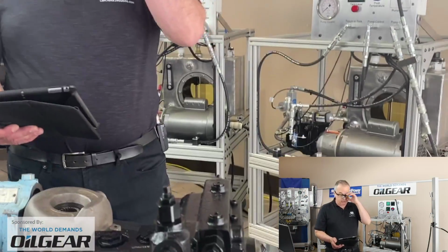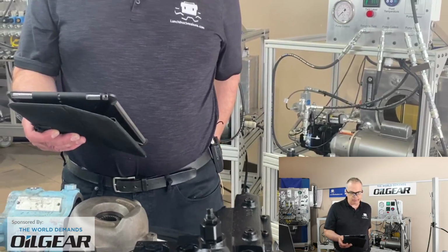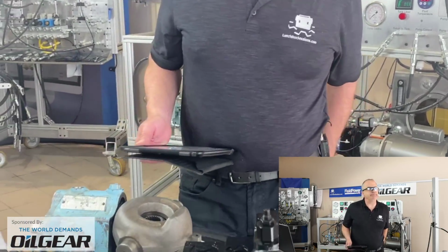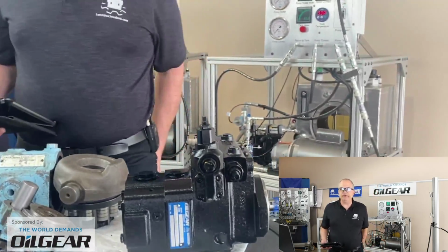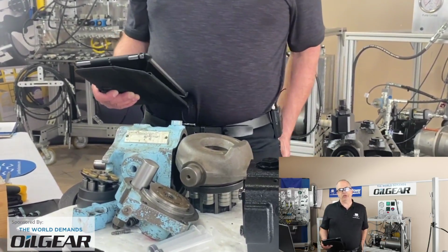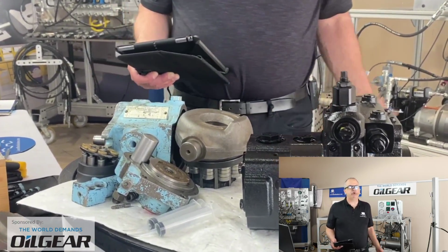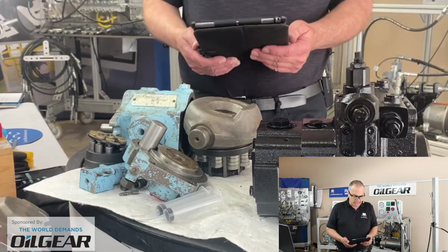Thanks for being with us. Black Cone says, what's the main application for piston pumps? Well, piston pumps are a fairly good heavy-duty pump. Perhaps gear pumps can take more abuse. So if it's all about abuse, perhaps, and not about energy savings, perhaps one would choose a gear pump, which is common for hoists on haul trucks and all kinds of very heavy-duty applications.